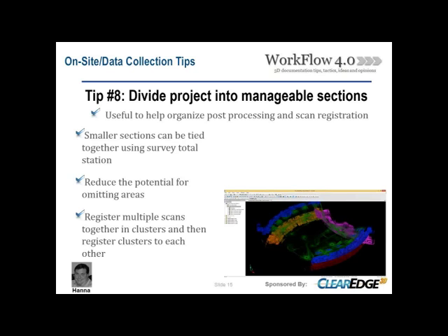When you get into large projects, break it down into smaller manageable pieces. Don't be so overwhelmed. When you're doing a stadium, an airport, it can be real overwhelming. Try to break it down into smaller manageable pieces, which will be useful in organizing the post-processing and registration. Carefully plan all this out. Scan in smaller sections, and then utilize survey control to tie those clusters all together.